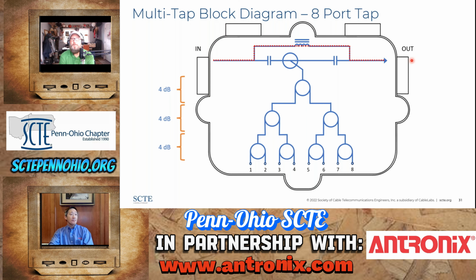Right. And so it's important to note that if you change a tap, you need to change it like for like on the faceplate value, or consult your design department before exchanging a 23 tap and putting in a 17 tap, right? Correct. Because the amount of insertion loss is actually different, and there are certain tap values where the insertion loss is all of the signal because they don't actually pass power. We would call those terminating taps, where they don't actually have a directional coupler in them. Right. They divert all of the signal to the tap ports.